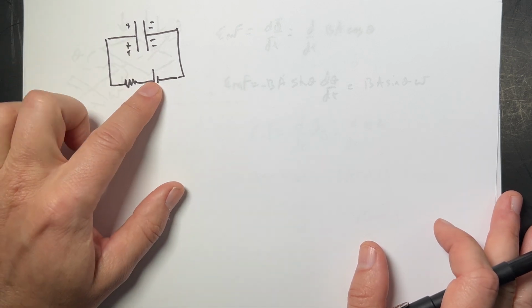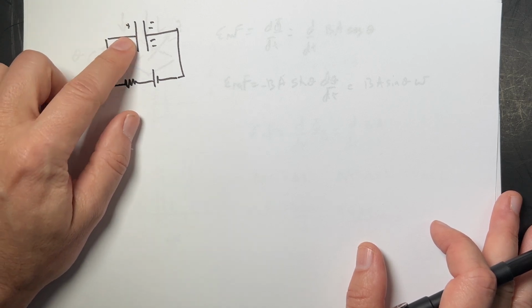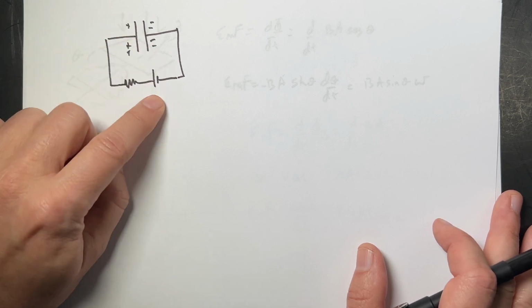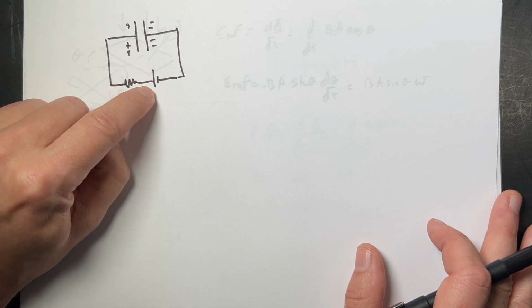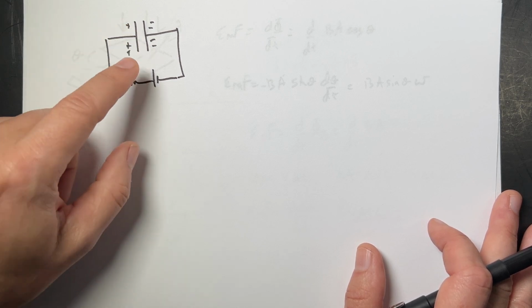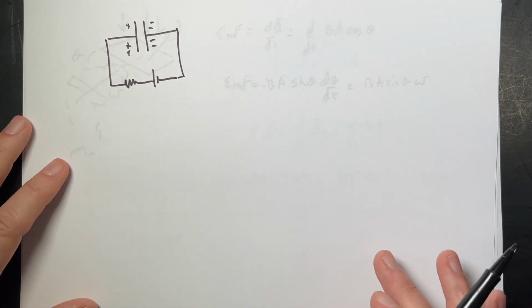Now, if you had an alternating current source, you'd put charge on, take charge off, and it would never fully charge up, and it would not equal the potential over here, so you'd still have current. And in fact, if you have a high frequency source, this acts like it's not even there. At a low frequency, it acts like a short, like a break. Okay, and that's a capacitor.